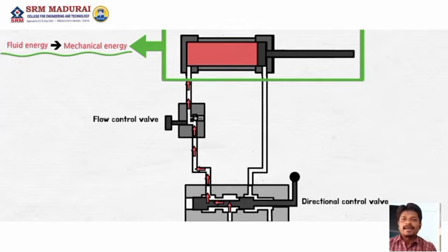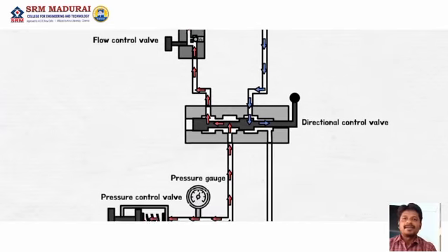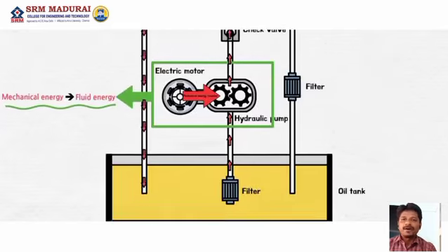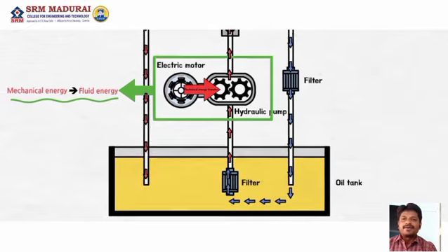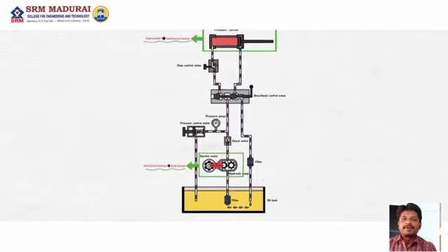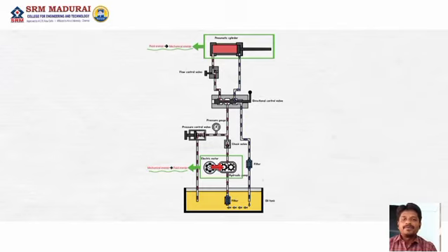The hydraulic oil that has completed this process will return to the tank through the valve. The hydraulic oil in the tank is soaked up by the hydraulic pump to become high pressure oil. The process is repeated to allow the actuator to operate repeatedly. This is how we generate and control large mechanical energy with only a small amount of force through a system process using hydraulic oil.